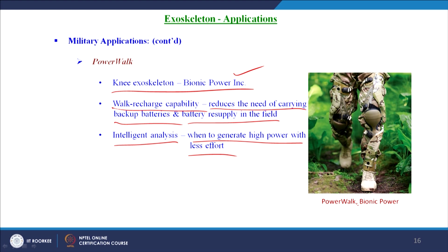It has a gearbox to increase the knee rotational speed for efficient power generation. A generator incorporated in the system converts the mechanical energy into electrical energy, and this electricity is converted for battery charging by a state of the art power conversion circuit. Then the soldier wearing this exoskeleton can recharge his lithium ion batteries with the electricity converted by the power conversion circuit in the exoskeleton.